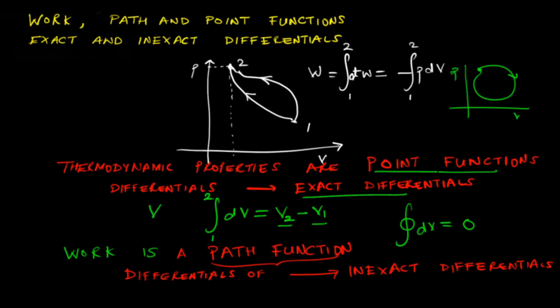For the same reason, when we denoted differential work in the previous lecture, we did not write dW, but we struck out this d with a horizontal line to denote that the differential work is an inexact differential. So exact differentials are denoted by, let's say, dV, which is the differential volume, and inexact differentials are denoted by d, which has been cut by a horizontal line, W. You will also see an alternate way of representing this, and that is delta W, and any notation is fine provided you use it consistently.